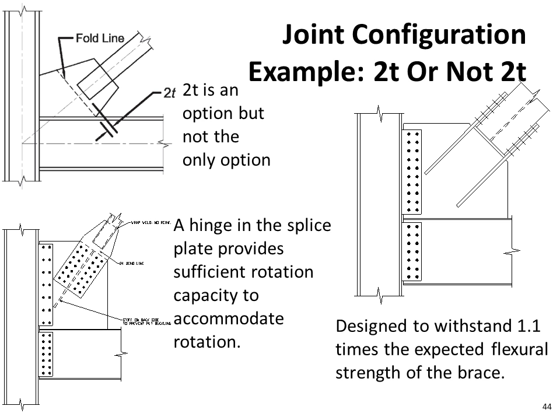I mentioned that the Code of Standard Practice has requirements that the engineer list any restrictions that they put on the type of or configuration of connection details if they're delegating connection design. Section A4 reiterates that, and then D1.8 also, relative to welding, reiterates that sort of requirement. Where it comes up a lot is, again, it almost falls under those imagined requirements. So this is just an example. There's other examples that could be used, but for time I can only really hit on one thing.